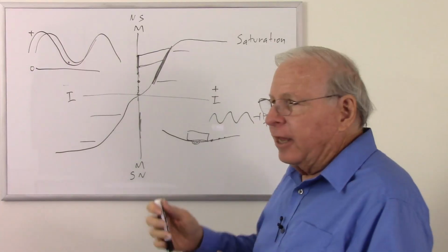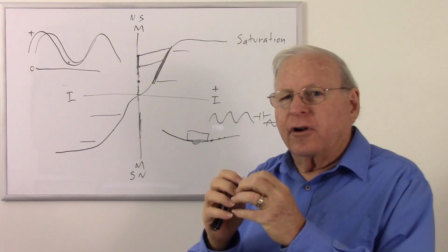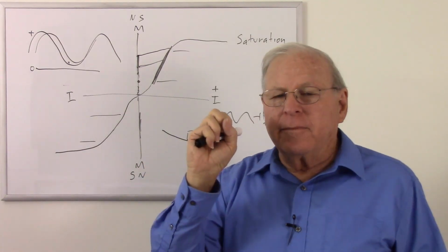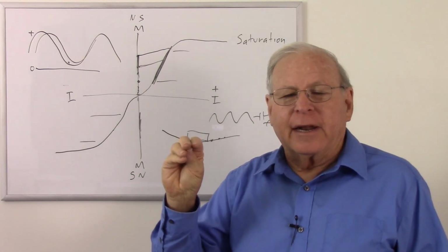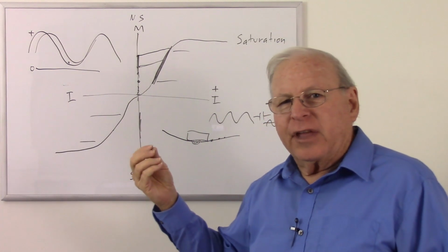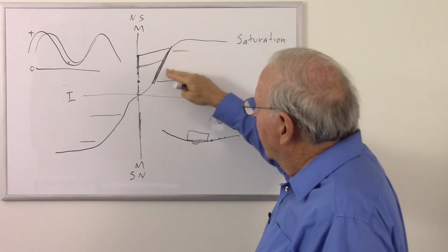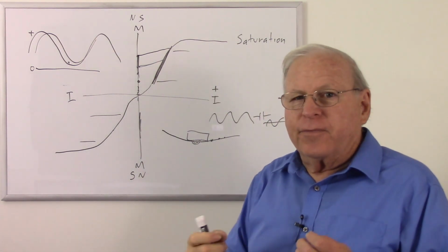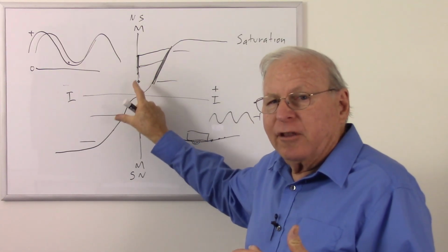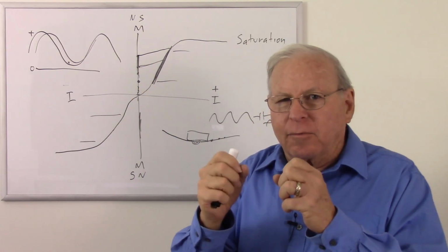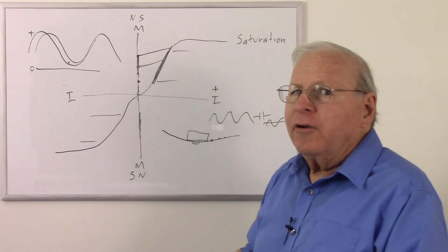As we magnetize the medium, we have these tiny molecular-sized magnetic domains that are magnetized, and they're strongly magnetized. They're going by this head and basically causing tiny bursts of magnetic energy. We don't want that, and those tiny bursts of magnetic energy coming at random come out as a hissing sound on the playback. This is because all of our magnetized domains are fairly strongly magnetized up in this area. If we could somehow move this down to here, we would have much less noise because the domains would not be as strongly magnetized. So as they go by, we get little bursts as these domains go by, which comes out as hiss. So how do we get rid of that?